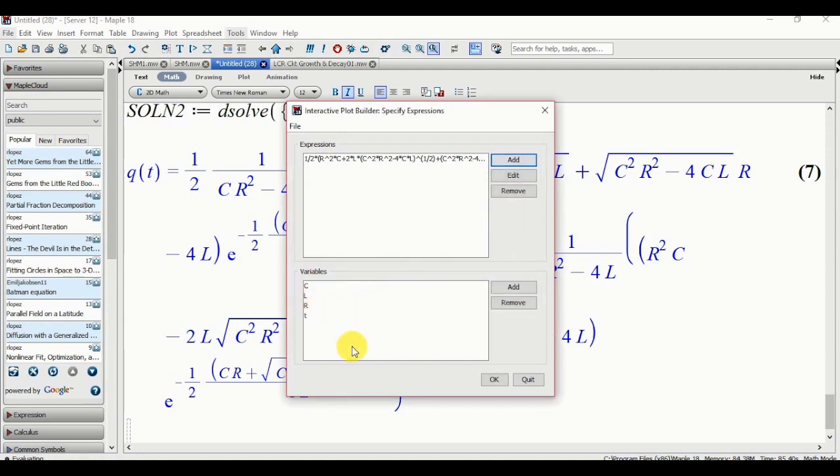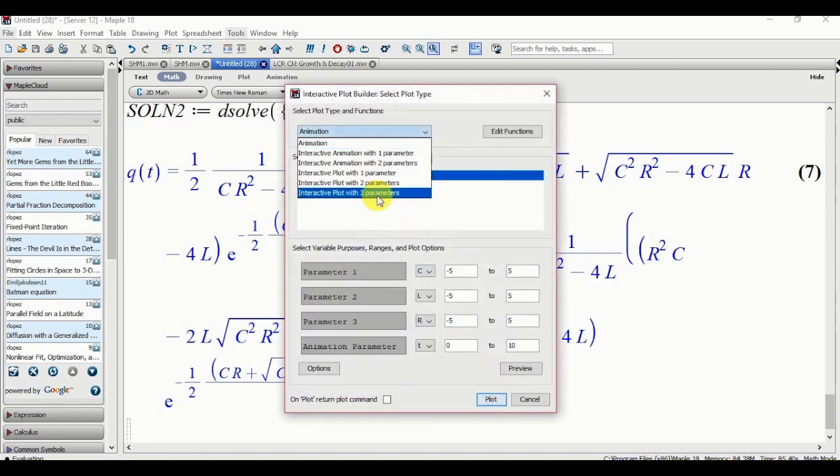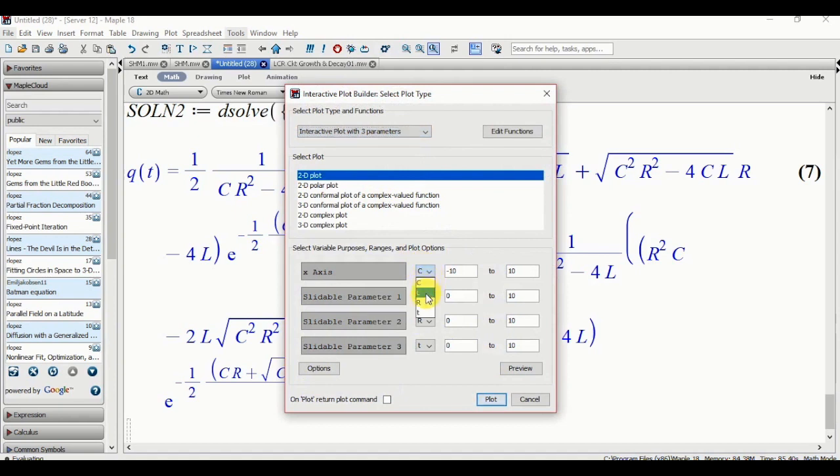Now this time E is not appearing in the circuit, but definitely the decay in the circuit will depend on the initial value. We want 3 interactive parameters. On x-axis we want real time, which can roll from 0 to say 1, and L, we shall try better values, 0.001 to 0.01. R we can select from 0.01 to 1, and C we shall select 0.0001 to, this should be a smaller value, and the other one should be higher value, 0.123, and then 1.